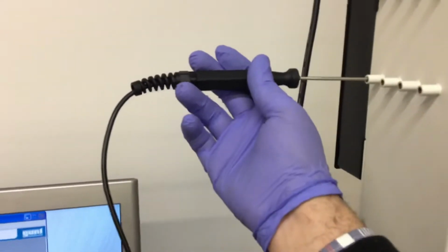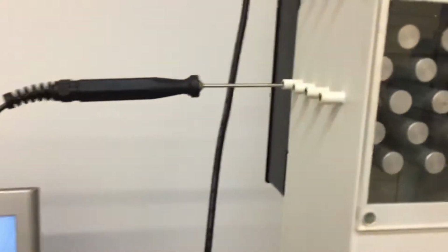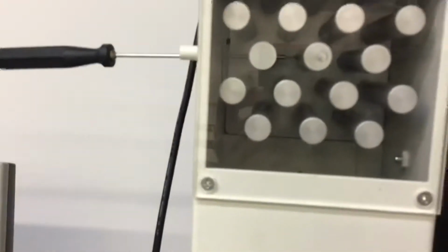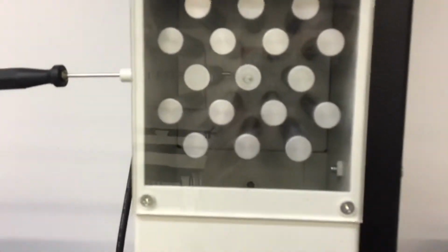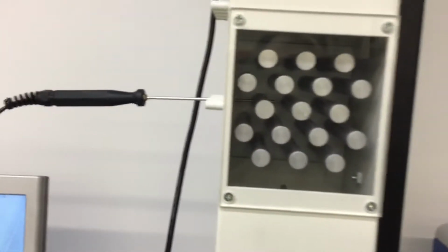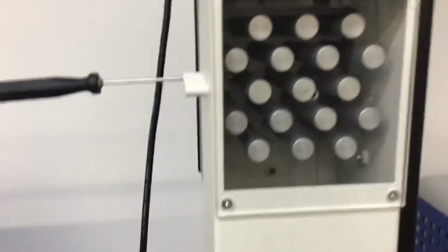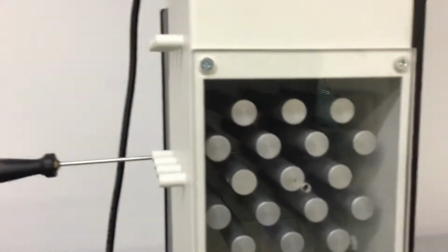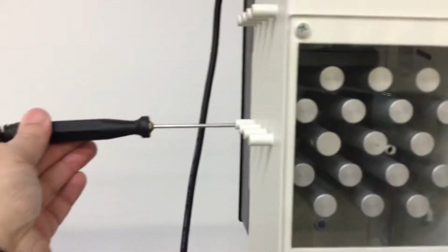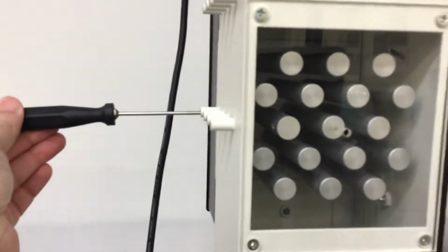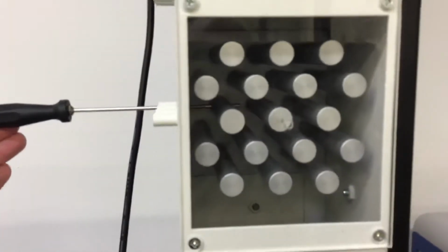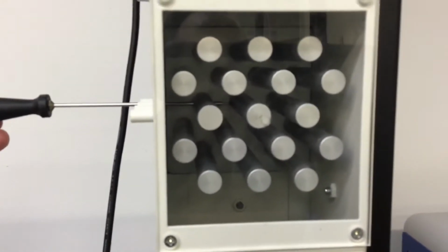one way to access this is through the side walls. And you can see here I have direct access to the middle part. I'm trying to get the average value of the surface temperature, so I'm trying to get to the base as much as possible. If I have good contact, and students are required, when you get to steady state, to align it and give it a little bit of a push. It has a spring there to make sure you have good contact with the surface.